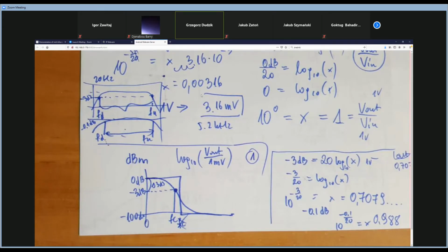We can. However, a DC converter works in another way, because for DC converters we have to get the DC signal on the output. And we have to filter the switching signal with a very low pass filter to get very, very low ripples and, on the output, an almost fixed DC signal.